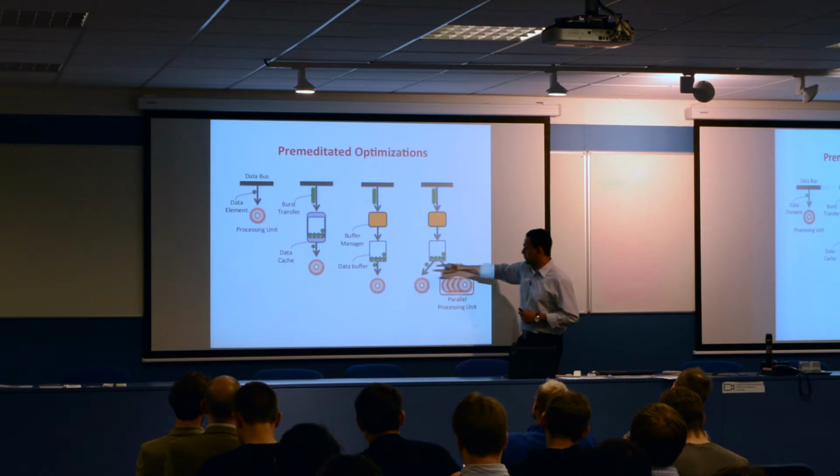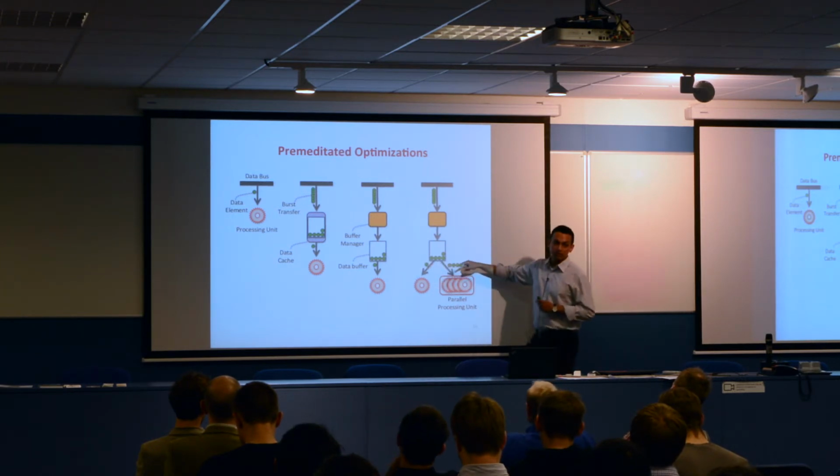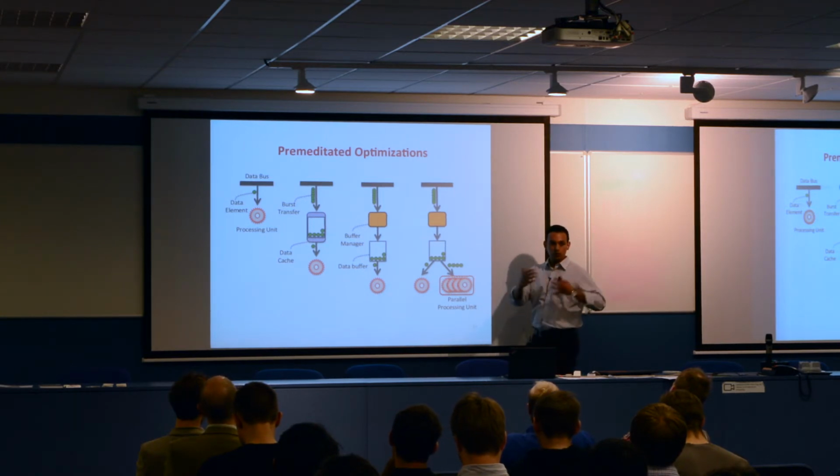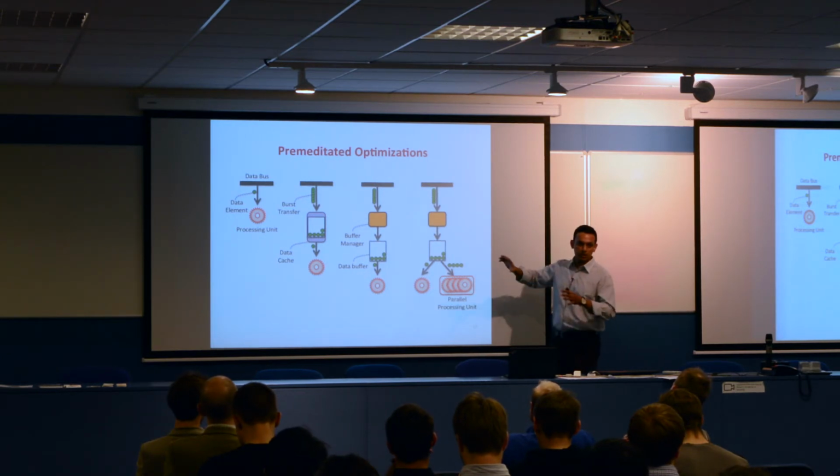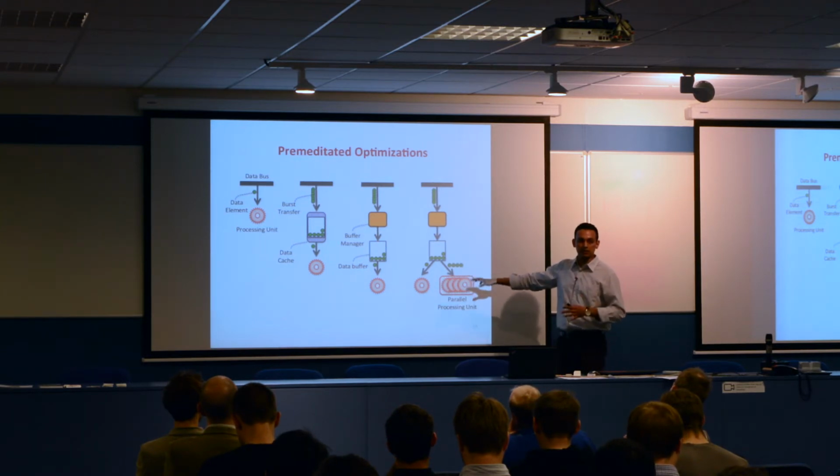Furthermore, if I know there's explicit parallelism, sometimes the high-level synthesis tools don't use the parallelism unless you reformat the code correctly. So I can explicitly format the code so the parallelism is completely revealed. Using all these tricks, we generate a bunch of different patterns. That's essentially what I mean by premeditated strategy optimization.